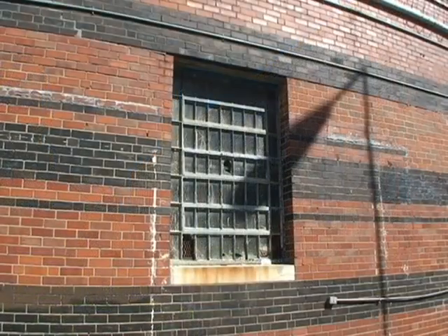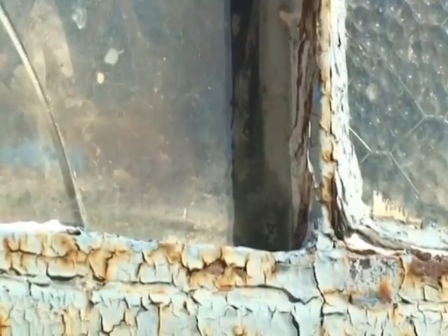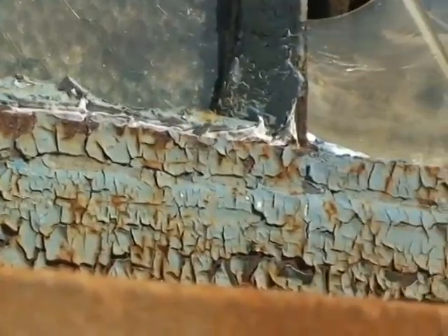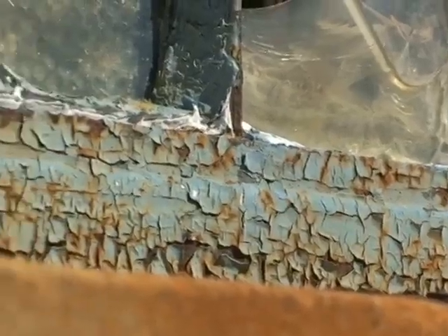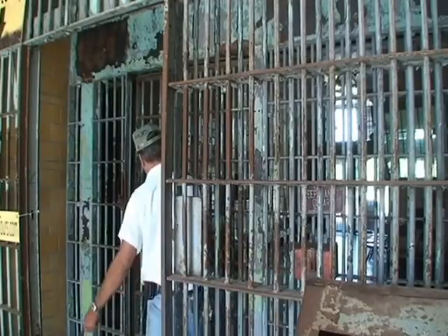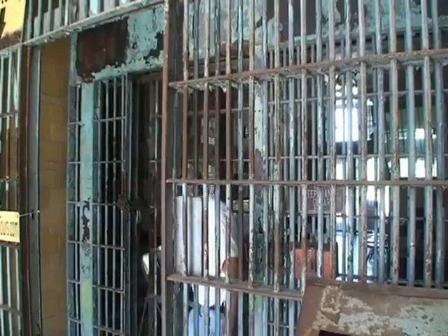All right, asbestos-containing materials you can find on the exterior buildings include window glazings or window caulks. If you look at this building here, you can see it's got blue paint on it. It's starting to alligator. Usually that alligator paint is another symbol of, or it's symptomatic of, lead-based paint as well. So we've got two issues here, both asbestos-containing materials inside the caulk or the glazing, as well as the lead paint component.